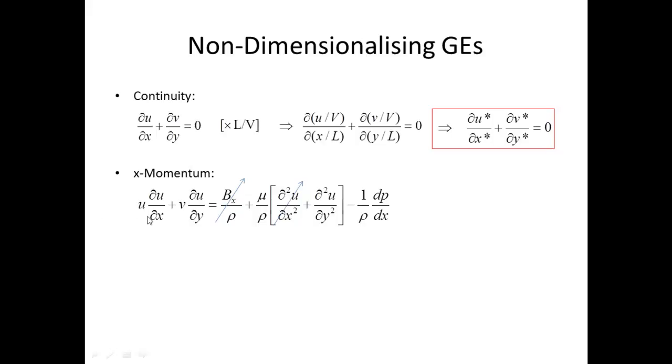See that we are not neglecting this component because it gets multiplied by u, so that it becomes an appreciable number. Likewise, even though we are having v here, we are not neglecting this term because we have dou u by dou y. So it's a product of a large term and a small term. Similarly, here also it's a product of a large term and a small term. So we cannot neglect anything on the left hand side. On the right hand side, we are neglecting the body force and the second derivative of the x component of velocity.